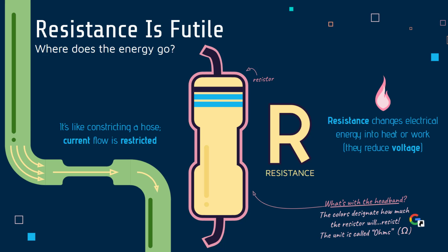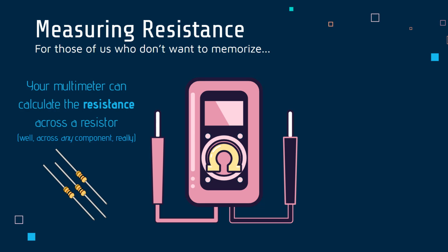Before, when we were using our multimeter to explore continuity mode, you may have noticed that the continuity symbol was found near a capital Greek letter omega symbol. This multimeter mode will allow us to measure the resistance of any given resistor, saving us the time and effort of memorizing a resistor chart. Although, one may argue that memorizing the chart will save you more time in the long run than using the multimeter every time you come across a resistor.